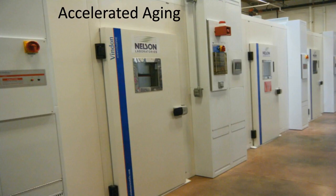Lastly, let's talk for a moment about aging. Real-time aging is required at normal storage conditions. Packages would be stored for the expected shelf life or use by date. Then they would be tested for strength, integrity, and microbial barrier properties. Since real-time aging for 5 years takes 5 whole years to do, accelerated aging is usually done as well so that data can be generated faster. A 5-year accelerated aging takes less than a year to do, which is much better if you're trying to get a product to market. There's some special considerations to remember, though, about accelerated aging.